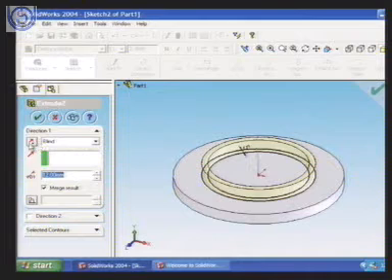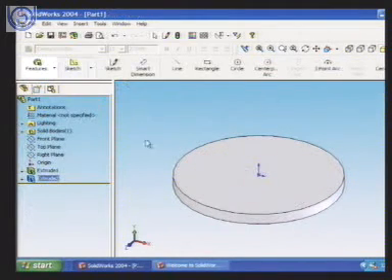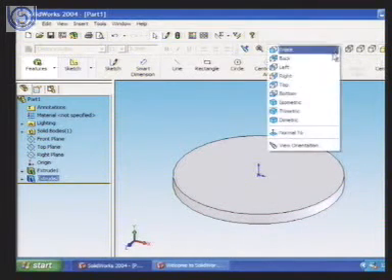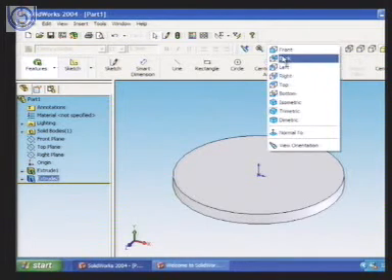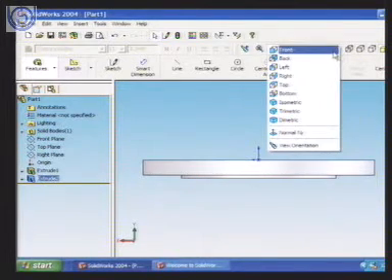Had I changed the direction, it would have gone down. So what will happen if I say okay? It will remain plane because I have taken it in the downward direction. So when I see the back view or front view, that time we will see this thickness. It is at the bottom because we have extruded it in the other direction.